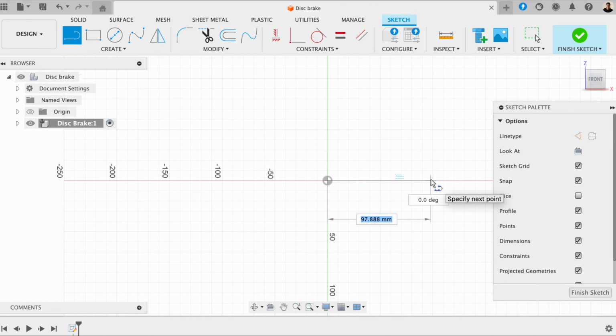And you can see, highlighted in blue, that my dimensions are already highlighted. So this means I can type in a number on the keyboard, and it will put it to that dimension. So the dimension that we want to use here is 131. And then I want to press enter on my keyboard, and that will draw my first line.